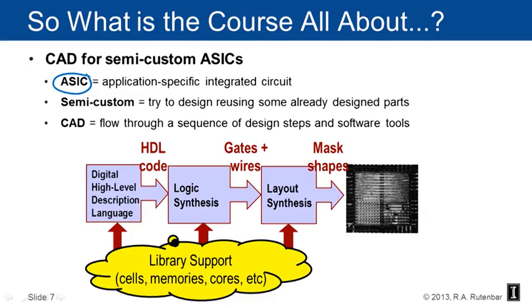What we're primarily focusing on in this class is that the central objects are basically the gates and wires. So logic synthesis starts with some sort of a Boolean description, gives us gates and wires. Layout synthesis takes gates and wires and arranges them appropriately.